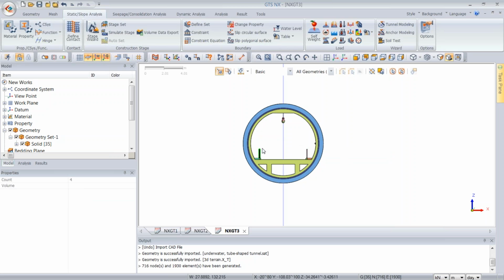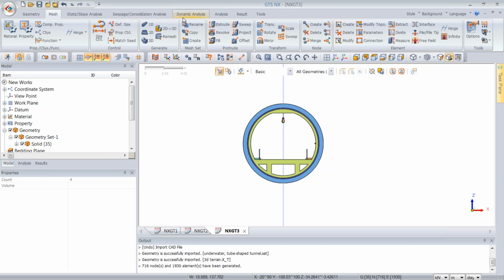So I can hide them by just clicking on them, and since we go through different layers, it's going to be different sets of these excavations. So we just want the solid of the tunnel when we mesh. We're not going to bother meshing the inside of what's going to be excavated anyways. In the third part of this tutorial, we'll go through the excavation construction process. For this case, we'll just keep it a static case, like if the tunnel was already finalized.